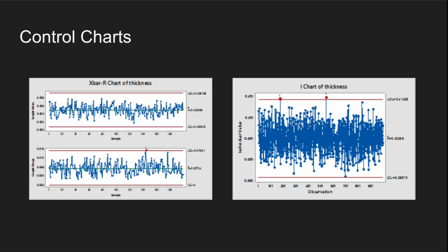The appropriate control chart for this process output is the X-bar R chart. This type of control chart is used to monitor the mean and the variation of the process when continuous data and subgroups of 8 or less, in this instance 5, are given.